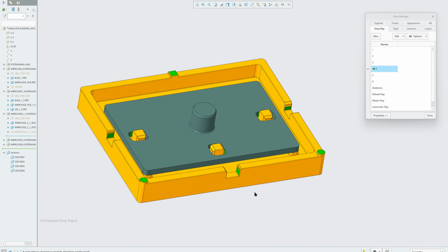But then again, let's circle back. Do we still have a predictable design? Now you've introduced new geometry. So we'll go to iteration 4, and whoo, luckily everything is still green. But again, the locating scheme has changed a bit. So again, we can drill down, and now the X constraining feature is moved to the center. Mm-hmm. And let's say that the rotation locks, they are placed here.